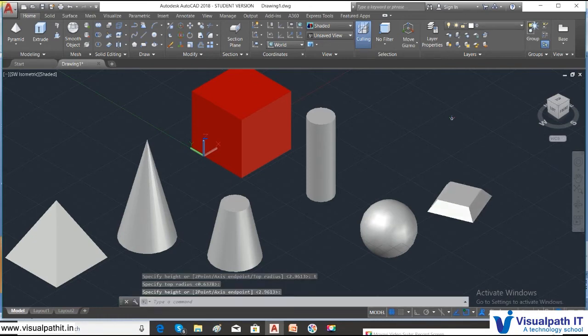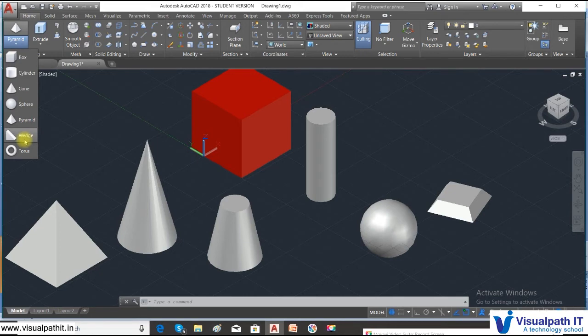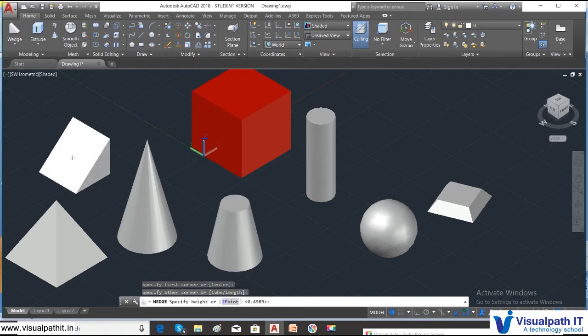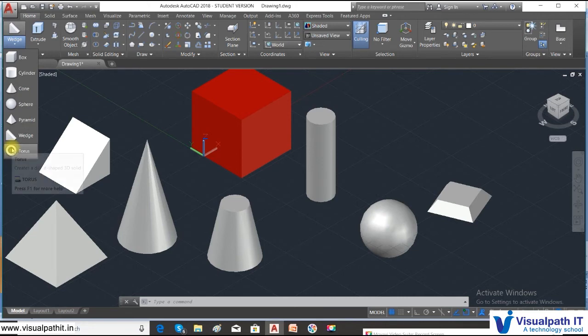So you can yourself see from these objects how many objects can be drawn. Pyramid. Then you have the wedge. Half pyramid is called the wedge. So specify the other corner, specify the height. Okay, so this is the truncated. It can be used for creating steps and all. So steps, other things, any other object that you can see, torus.